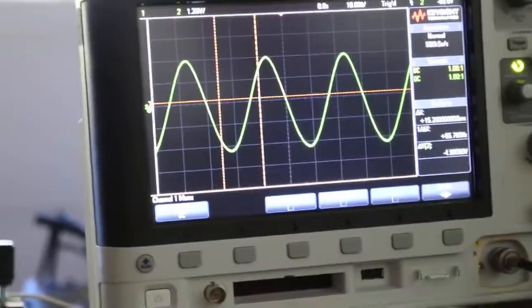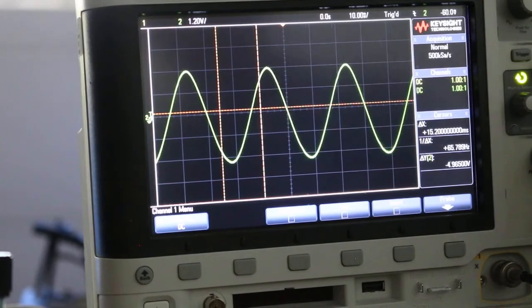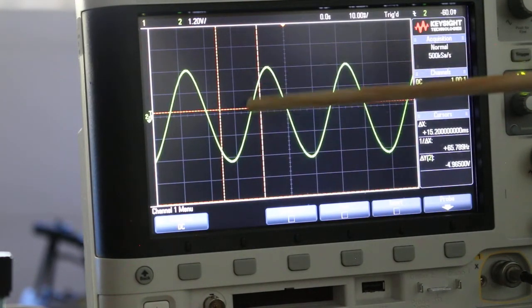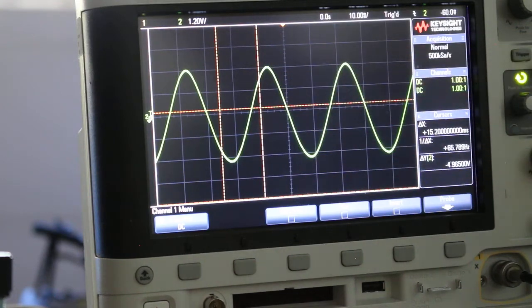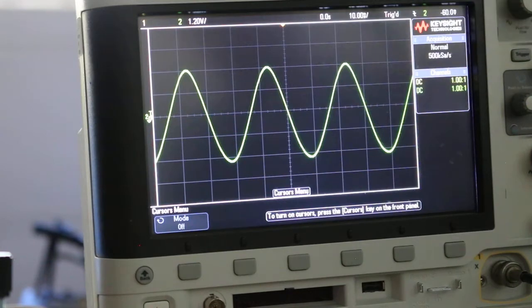One irritating part about this signal is that it is not quite symmetrical around 0, and you can just look at it here. If I put 0 right at the center of the oscilloscope, you see it's definitely higher for a smaller amount of time than it's lower, even if I turn these cursors off. That causes some problems in how useful this signal will be, so you'll see that when I use cursors to identify the resonances during the data taking videos.